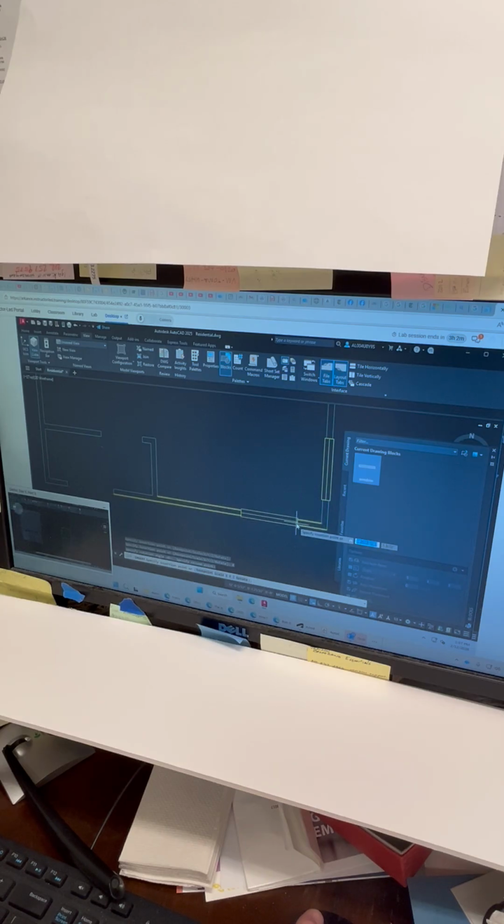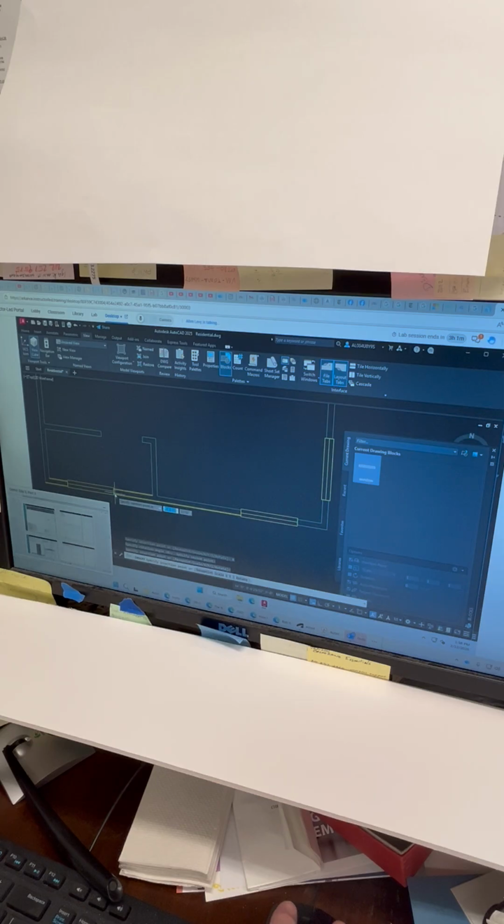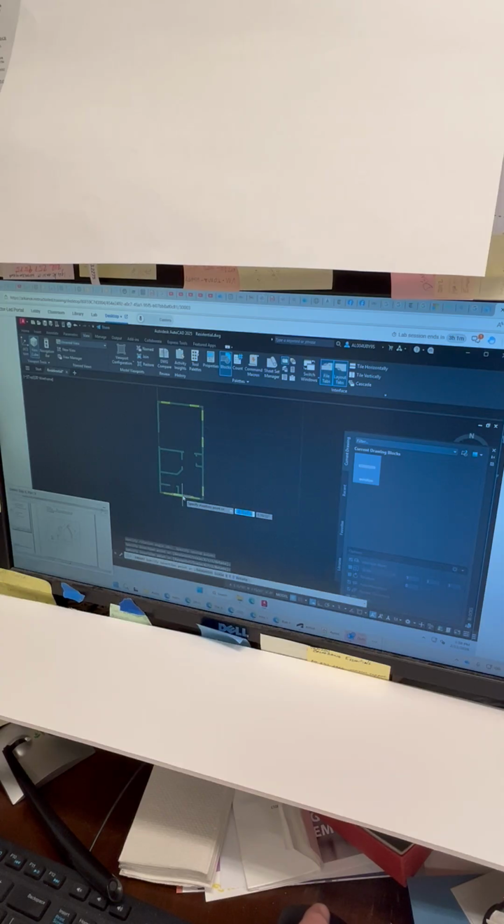All right. Now, I have another block that you've already created that I want you to bring in, and it is the door drawing. Okay? So before I get to it, look how this is now a block reference. It's easy now to select.